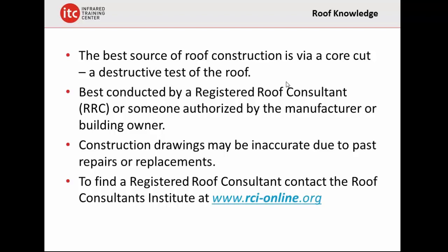But if you want to know the as-found, what are you standing on? The best way to determine that is with a registered roof consultant and a core cut test. Even if you have a manual that shows how it should be constructed, how is it actually constructed? Even if you had as-built drawings, that doesn't mean that's the as-found condition, because they might have torn that roof off and made some repairs.